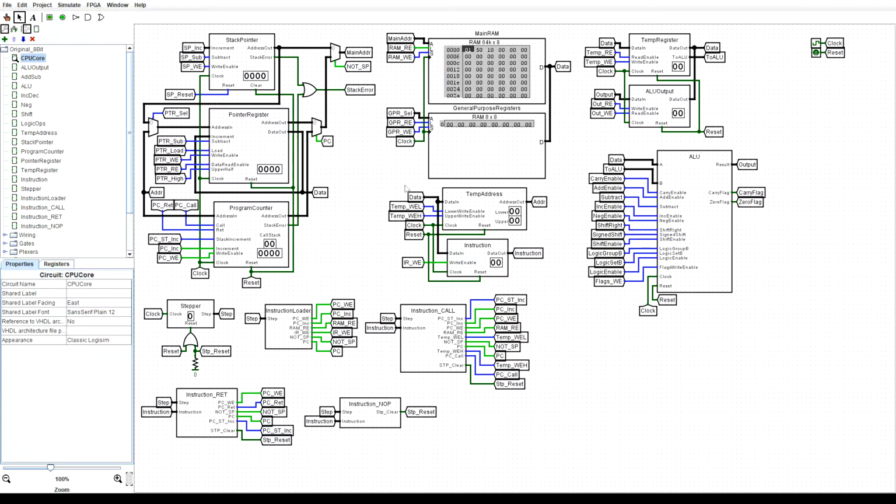It should be the first instruction called. At least the first instruction called if you use the stack, and if you also use the interrupts, which will be later in the series, then you initialize the interrupt lookup table as either the first or second instruction, with the stack pointer being the other instruction. By the way, you don't have to do that first, as long as they're initialized before they are ever used.